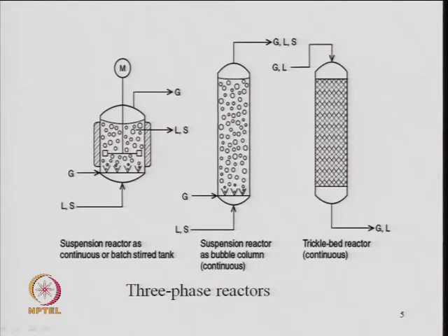So, the suspension reactor which I was discussing, I will just talk a little again on this. The suspension reactor is similar to a bubble column reactor, a continuous type of reactor. So, gas is being passed through the sparger, liquid and solid are already there, and liquid is passed from this. So, that is a slurry here, and the particles are kept in suspended form. So, again you need to decide what the particle size is, what the type of liquid is, and just like in a fluidized bed column, similar theory of hydrodynamic conditions is also required to be studied.